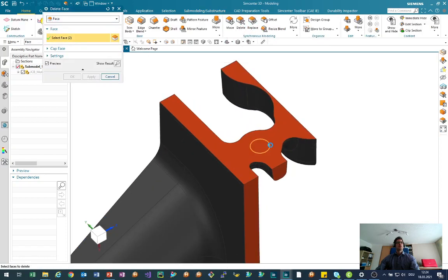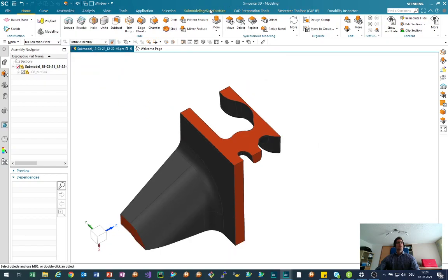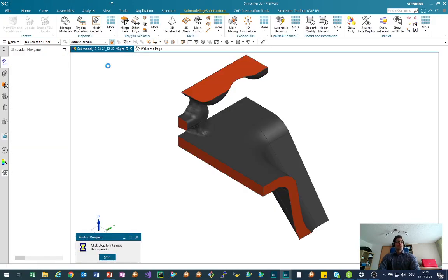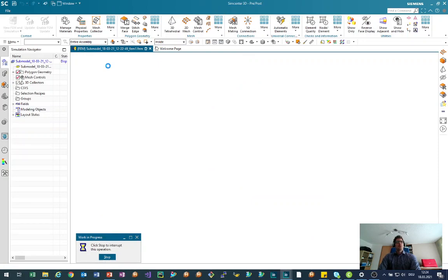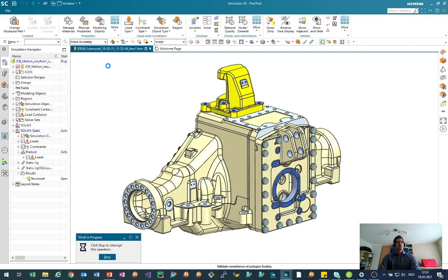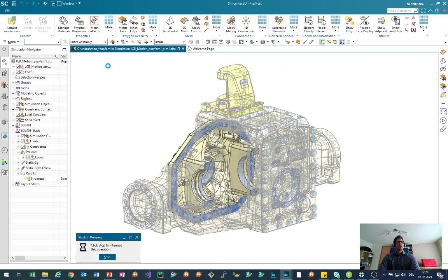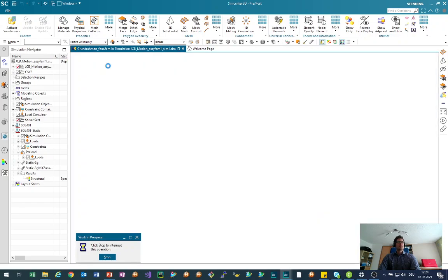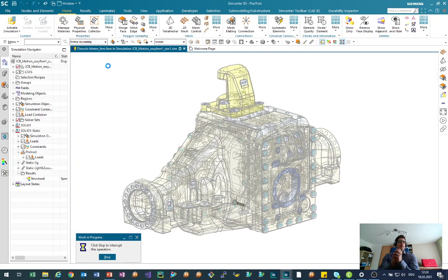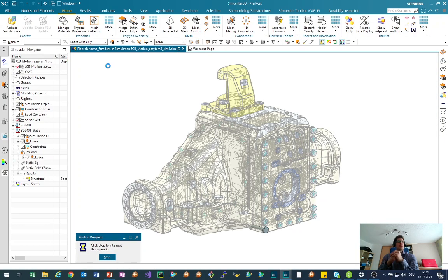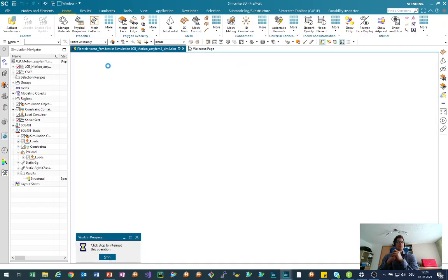There are some details in the structure that I want to neglect, and then we can switch to generate the CAE parts. As we do that, we will get the material that is defined and was created in the global model, extract that, and also apply it to the submodel. This is a process that you currently are seeing, where it loops through the assembly FEM and identifies all materials that were created. And we just have to select the proper one in the submodel.